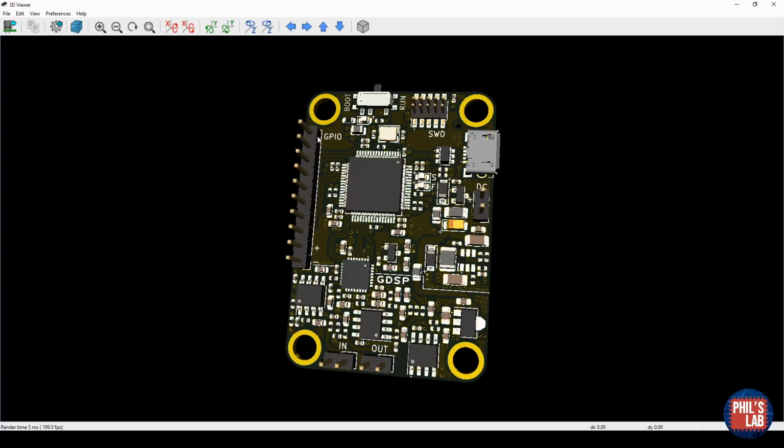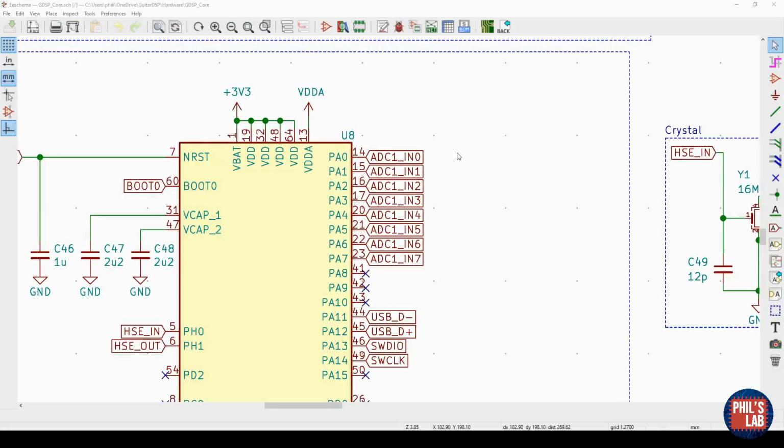So I'd like to show you how I can get a fixed sampling rate on these ADCs and also read this data in via DMA. Schematically, you can see I have about 8 ADC channels going in, and we might only be using a couple of them, but I'll show you how to read in, for example, a number of these ADC channels using DMA at a fixed sampling rate.